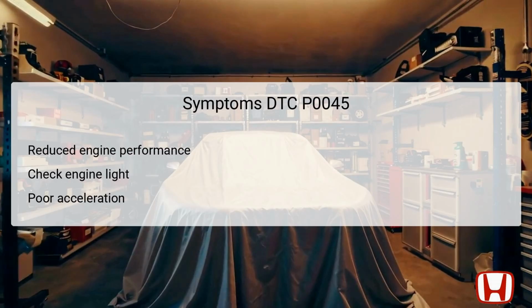The symptoms associated with DTC P0045 typically include reduced engine performance, manifesting as sluggish acceleration, and possible decrease in fuel efficiency. Drivers may notice the check engine light illuminated on the dashboard, prompting a need for further investigation. Other indicators can include an overall feeling of poor acceleration and inefficient power delivery, affecting the vehicle's drivability under certain conditions. Identifying these symptoms helps in narrowing down the troubleshooting steps necessary for resolving the error.